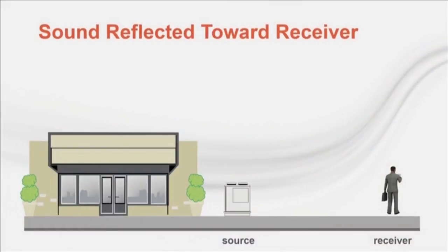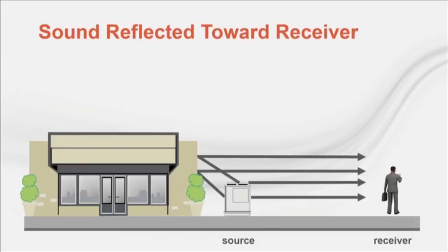The simple case of a sound source placed very near a large, flat surface can be accommodated by changing the value of Q to 4. This models the building as an infinite flat plane, which is a good assumption if the building is large compared to the equipment. For shorter or narrower walls, some sound will go over and around the building, reducing the sound headed toward the receiver. In most cases, this can be ignored.